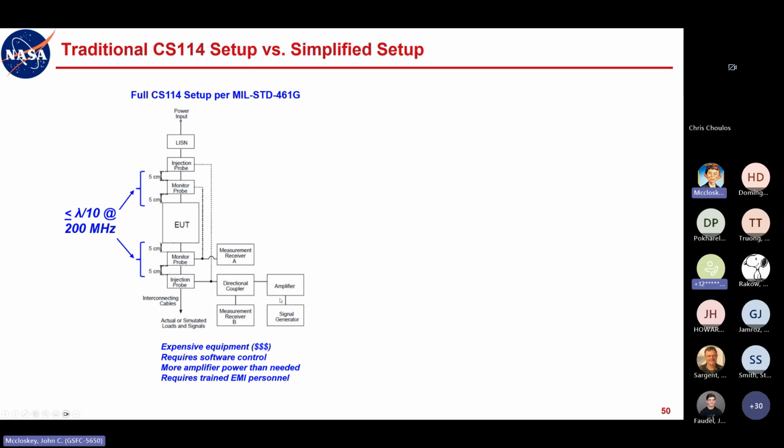Now, I think if my amplifier or signal generator crapped out, I probably would want to do my pre-calibration again. But the instructor of that class did point out, if you're monitoring forward power out of this directional coupler, and then at some point you have to replace either one of these pieces of equipment, what you're playing back against is your lookup table you've created of the forward power numbers as a function of frequency, and you don't necessarily have to repeat that calibration.